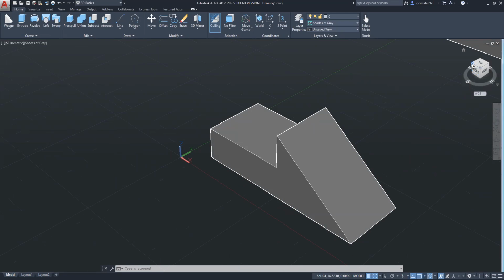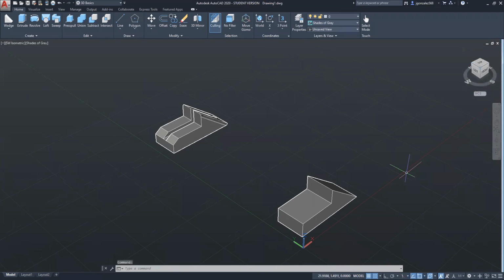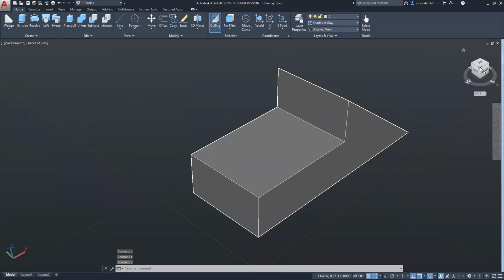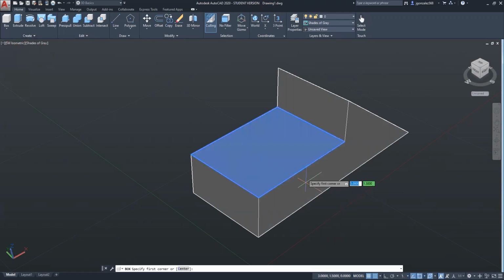So I'm going to adjust my angle here a little bit. I'm clicking the top corner of left and front so you can see the back. Use the box command. But before we start drawing, make sure you highlight. Since I wanted to go upward, see how this wants to be this kind of shape, going flat and up, not flat on the ground.